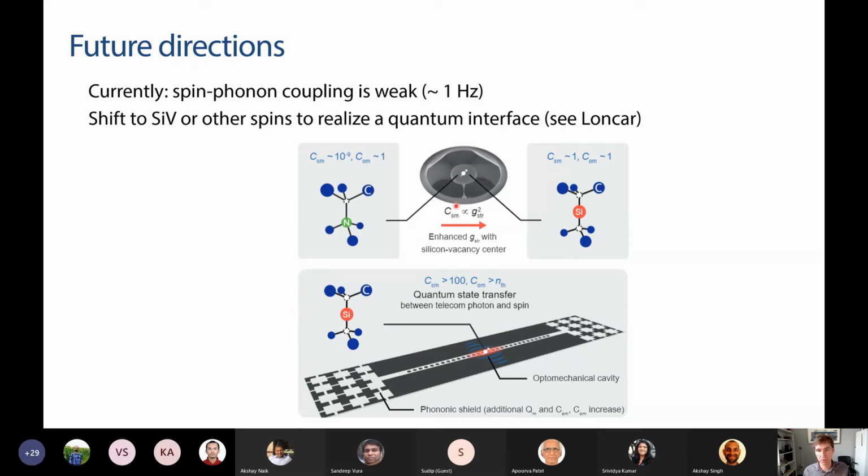So the idea was to make these, and we are working on that. But the fact that these microdisks support lots of optical modes, so they have a high Q optical mode every 20 nanometers or so, it depends on your diameter, this was important for letting us do all of the multi-mode stuff that I talked about. It would be hard to do that in the photonic crystals.